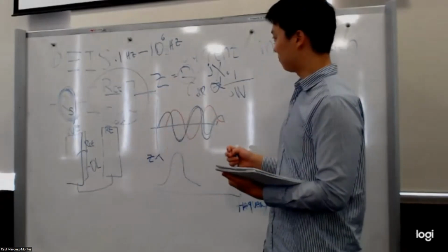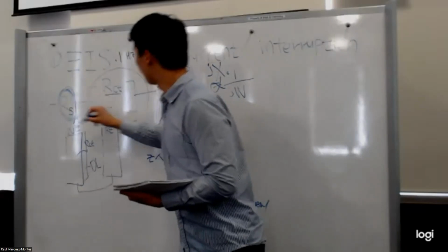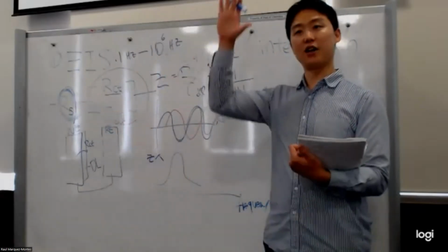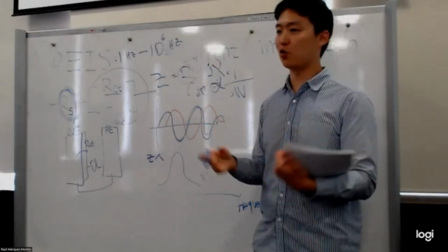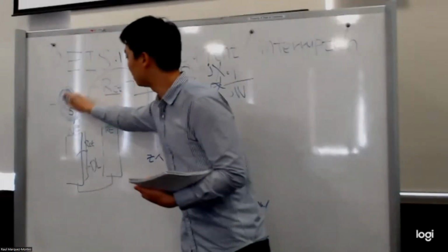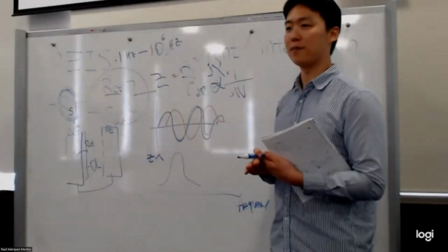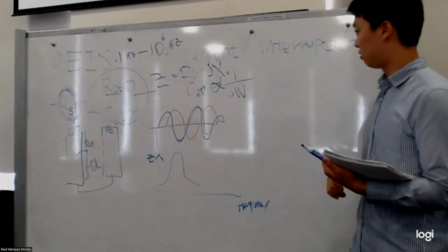And this single component appears at really high frequencies, like 10 to the 5 hertz, which is 100 or 1,000 times higher frequency. So that's how we can obtain this series resistance or uncompensated resistance, and it's most commonly used to calculate the RU value.